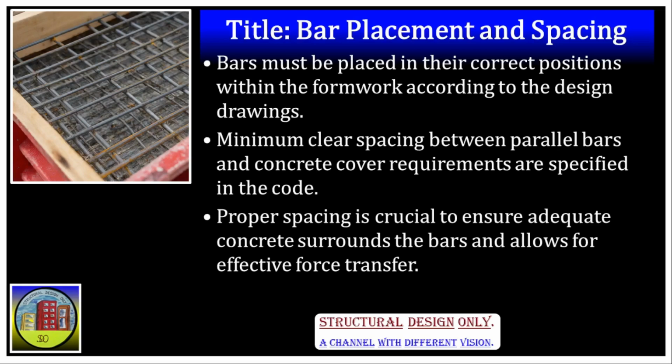Title of this slide is, Bar Placement and Spacing. Bars must be placed in their correct positions within the formwork according to the design drawings. Minimum clear spacing between parallel bars and concrete cover requirements are specified in the code. Proper spacing is crucial to ensure adequate concrete surrounds the bars and allows for effective force transfer. Following these guidelines, we can assure proper bar placement and spacing.